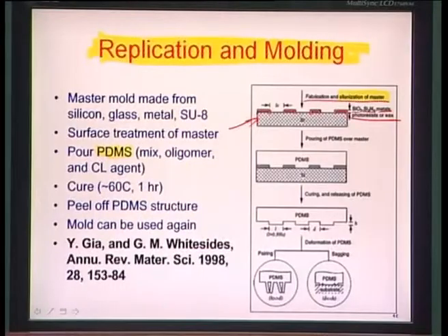And after this mold preparation process is over, you use polydimethylsiloxane, which is essentially a mixture of an oligomer and a cross-linker agent or a curing agent in a certain ratio by weight. The idea is that this is a compound which is liquid at room temperature, but if you mix or stir the curing agent well and heat cure it, it develops cross bonds, and it is like a growing epoxy chain, and so it becomes hardened and rubbery when such a heat treatment is carried out on the solution.